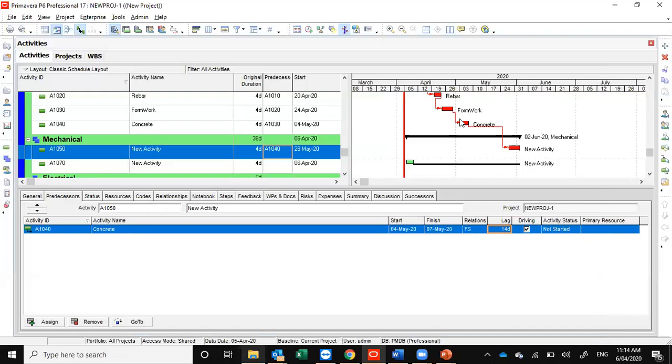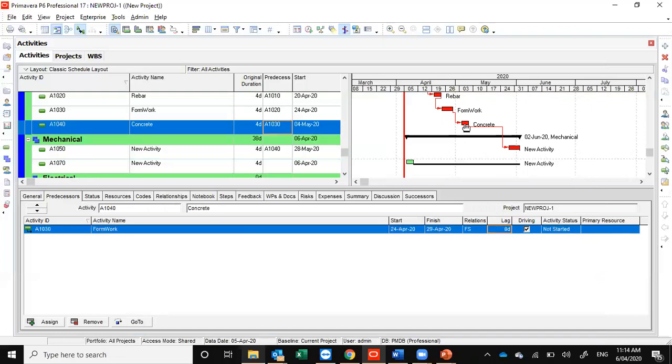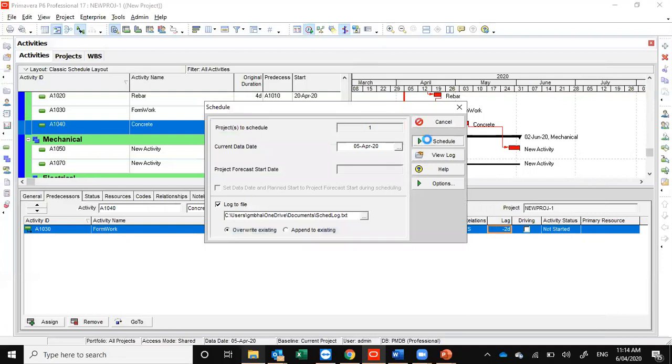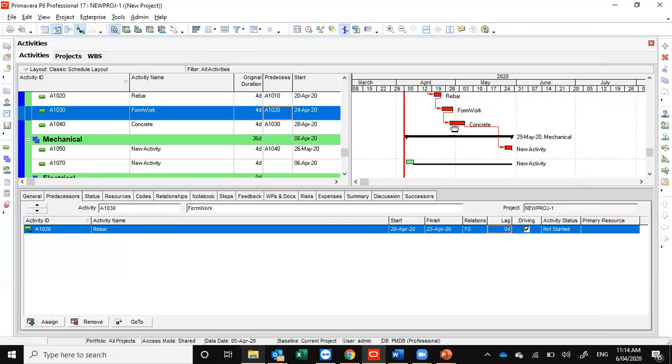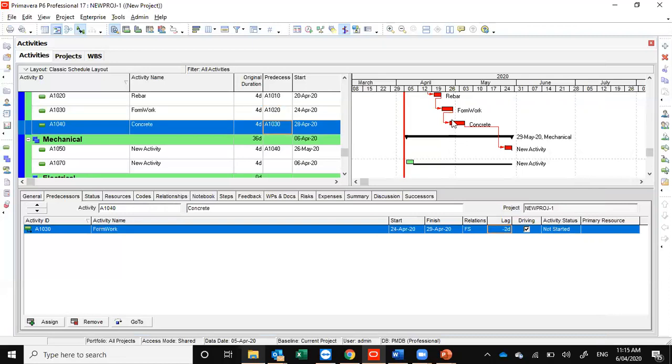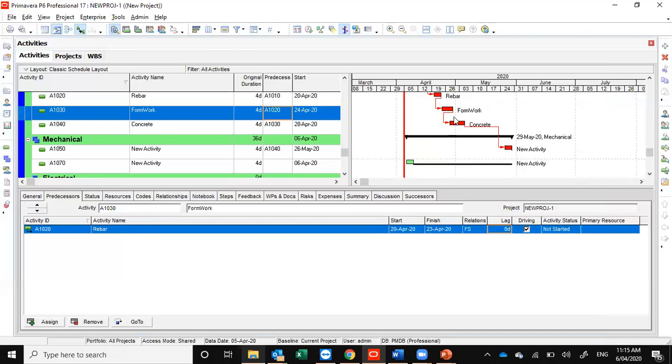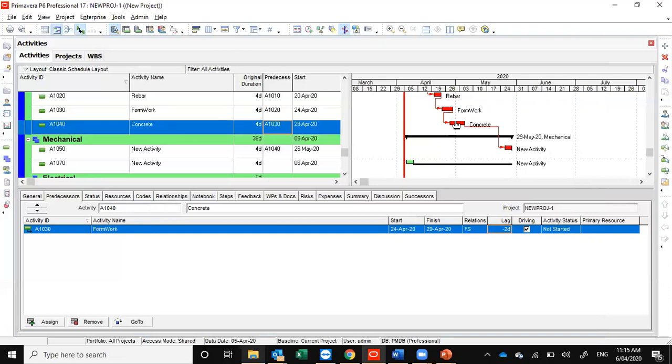And same as we have a lag, we have a lead. Lead is whenever you are able to start the activity without completing its predecessor; in that case you have to put a negative value in the lag. It will be considered as a lead. So mostly lead and lag is a very important aspect for mapping a relationship in Primavera or any PMI software. It looks like it's mapping over-allocated, but in that condition you have enough resources to optimize both activities simultaneously.